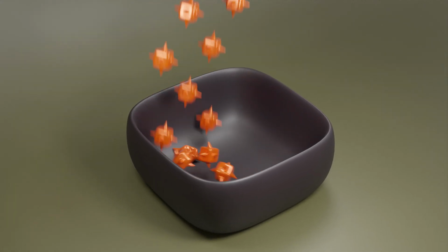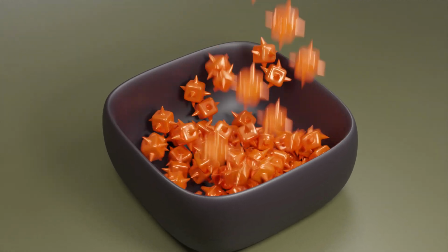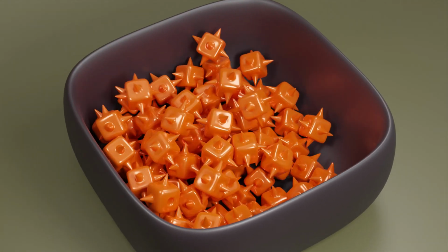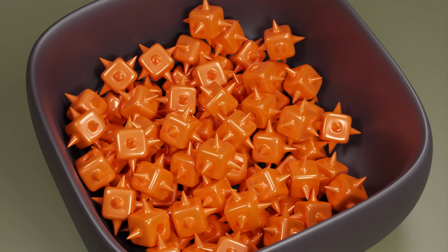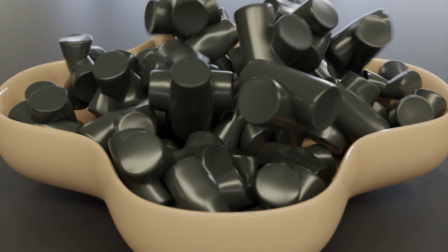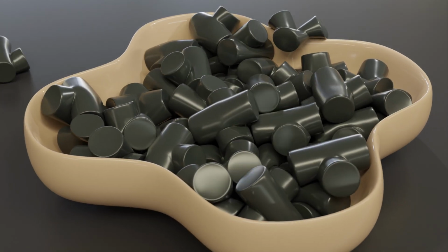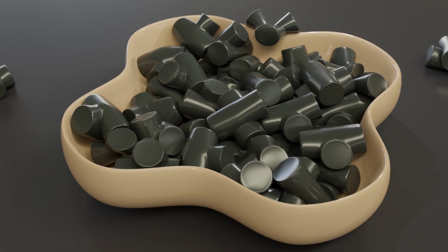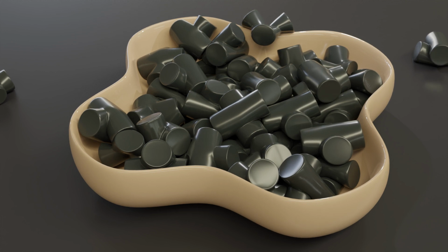Now, since we made the Rook, I've had a few questions about 5-spoked poles, what they do and why they're bad, so I thought I'd talk about them here. The first thing is, 5-spoked poles are not bad. They're essential to describe complex shapes. The problem is, a lot of modelling tasks leave them in the wrong place where they can cause a lot of trouble. Let's have a look at it in its simplest form.